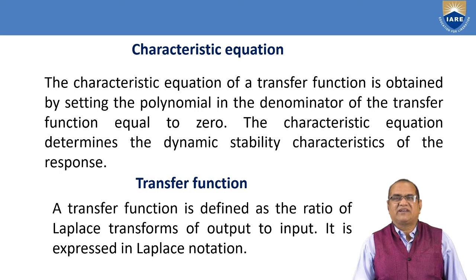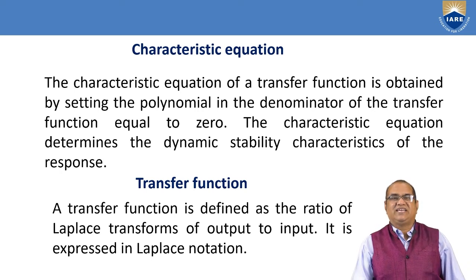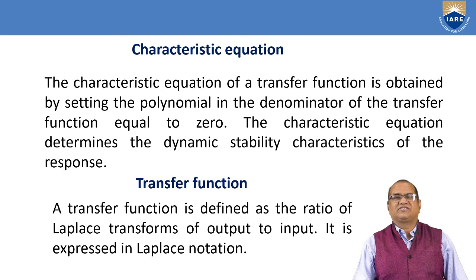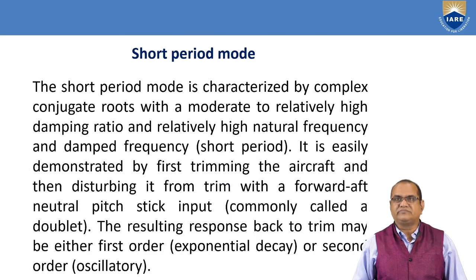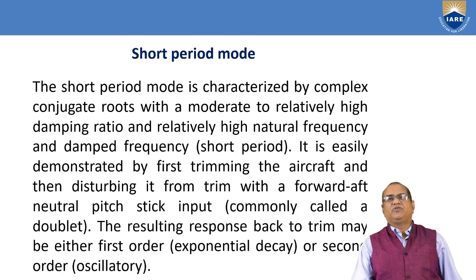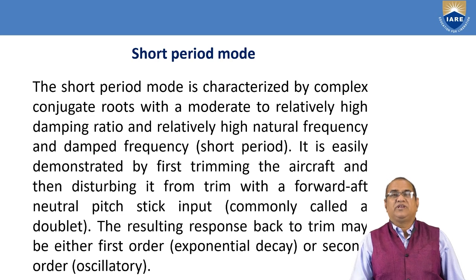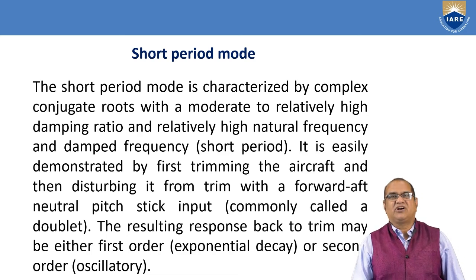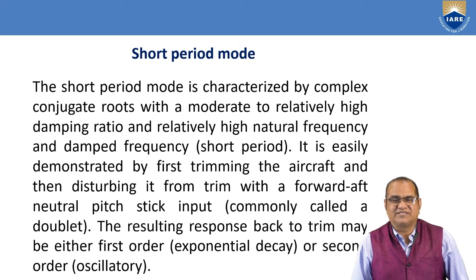Transfer function. A transfer function is defined as the ratio of Laplace transforms of output to input. It is expressed in Laplace notation. Short period mode. It is opposite to the phugoid. Phugoid is long period, and here is the short period. Within a very short time, the response is taking place.